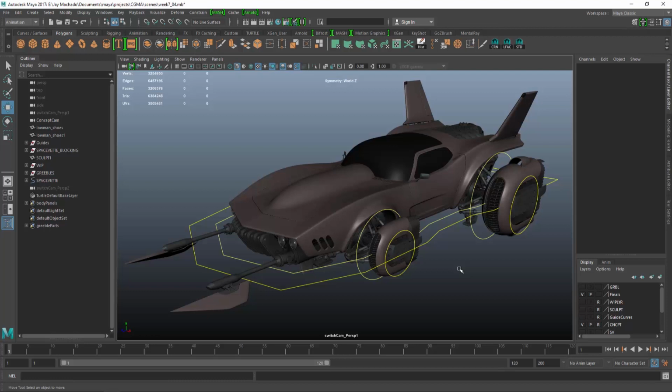While some of these rigging skills aren't necessarily required of a hard surface modeler, I think they are valuable workflows to know. I find these tools extremely valuable for designing mechanisms and illustrating how they function. If you set up basic rigs like this in film production, it's a toss-up whether the rigger will use your work or throw it away and start from scratch. I've literally had both cases happen to me. As I mentioned in the lesson, a lot of these workflows should be used when the model is fully completed. I would therefore recommend saving a version of your file before doing any heavy rigging work.